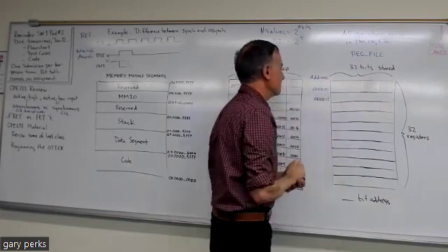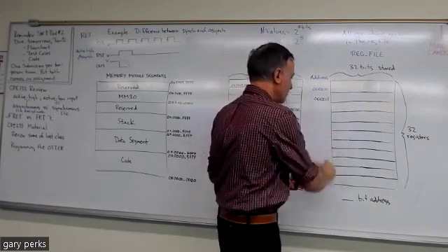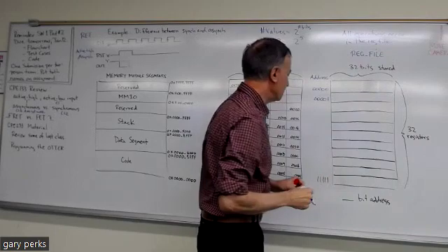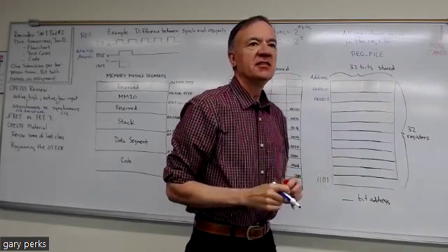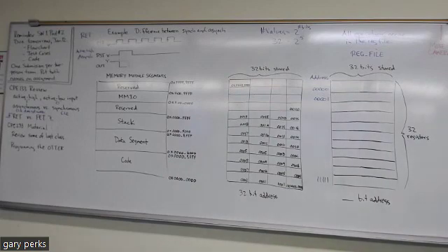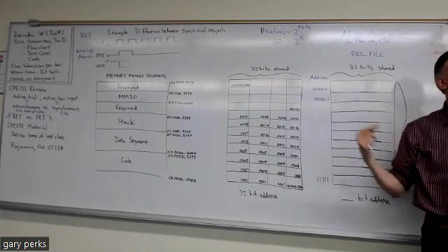X1 would have address 00001, and so on, all the way to address 31, which is 5 ones. When you're writing your software, we use X0, X1, and so on to identify the register we're using, but hardware-wise, it's known by a 5-bit address.